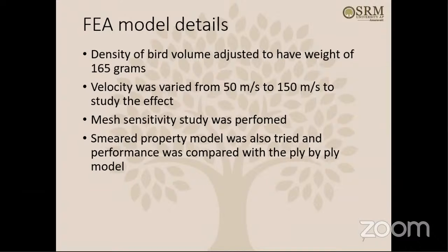If you remember the earlier requirement that I stated, it is a 165-gram bird hitting a booster blade. So you can adjust the density of the bird. Of course, there is a specific bird material that can be used. Bird is very soft, so in many literature sources a soft material is given for the bird.